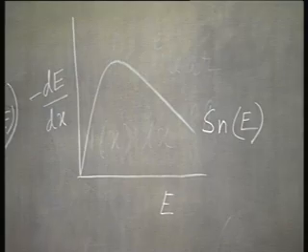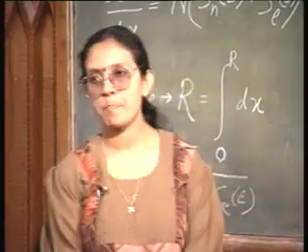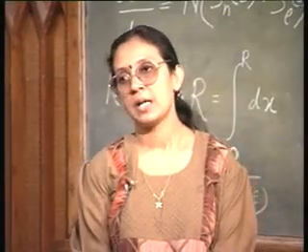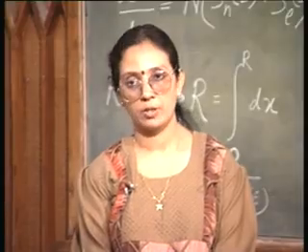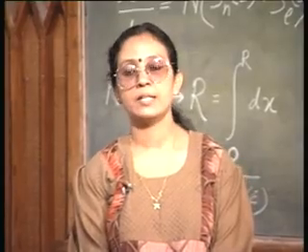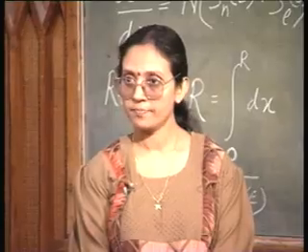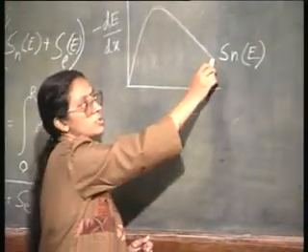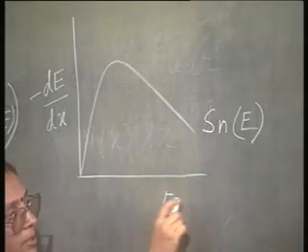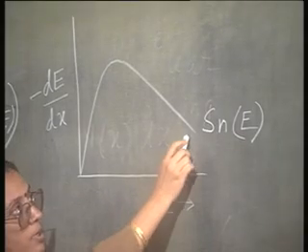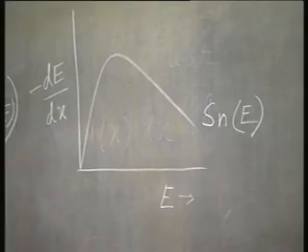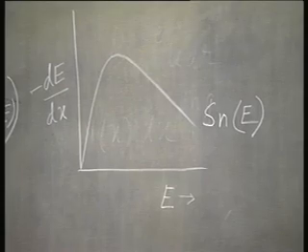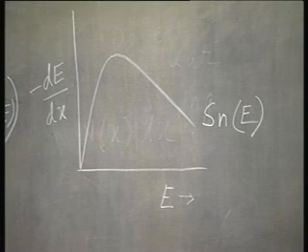What do you understand from this? When the ion is entering the semiconductor, at that point its energy is maximum, right? At that point you see the nuclear stopping is relatively less. Remember this is E. So, this is the point where E is high. When E is very large, the loss of energy, the transfer of energy to the lattice atom is a relatively slow process.